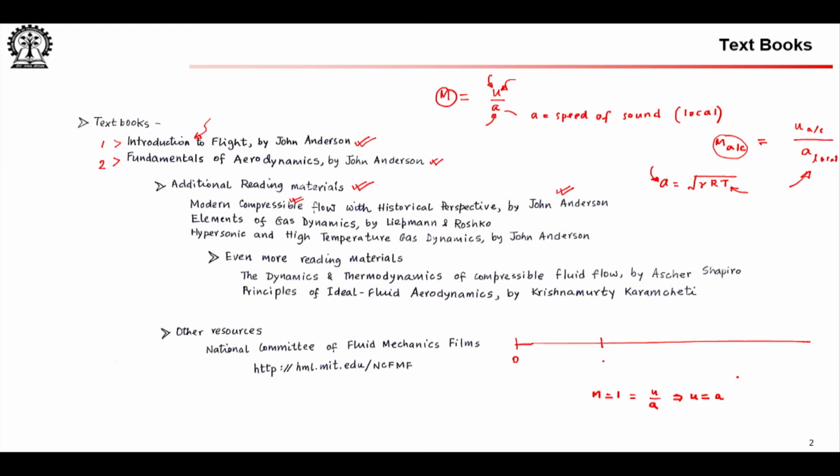So, it is an introduction to aerodynamics, so we can introduce all these things. If you have crowded cities, you will run into the problem of sonic booms and the problem of aeroacoustic noise. Sonic boom is essentially for supersonic aircraft, you have shock waves, and when the vehicle is flying close to the ground, these shock waves can impinge on the ground, and where they pass across, for example, it can shatter the glass of the windows, etc. So, it is often a major challenge to have supersonic airliners land in airports in crowded cities.